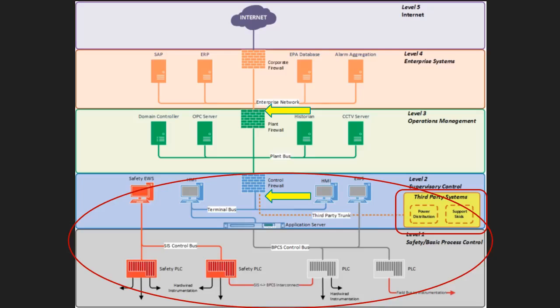They need to sit on your network. They need to have direct level access to your PLCs, your engineering workstations, your historians, things like that. So that right there is going to be a key component of how you segment and operate your network. And again, those are your key firewall points.